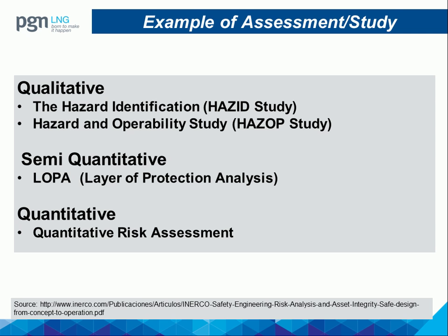As I say, this is the example of assessment study. It's qualitative. For example, HAZID study and HAZOP and operability studies. Why does it say qualitative? Because there is no number. You don't need to count it. It's basically based on the skills of the people who do the assessment.